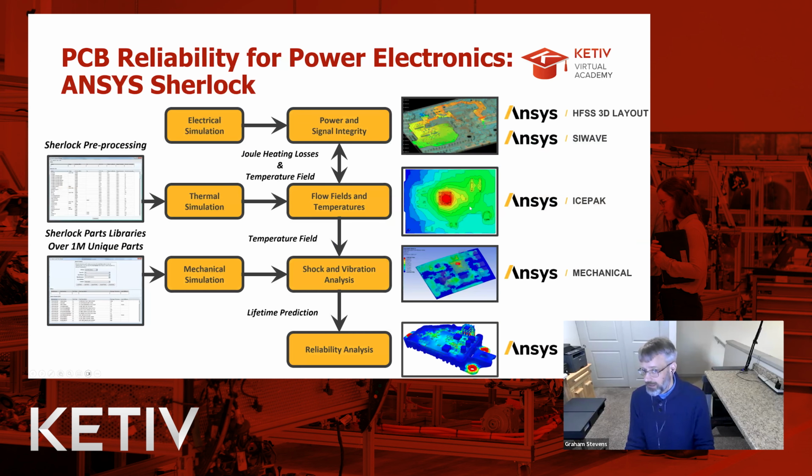And then finally, there's Ansys Sherlock for reliability, where we take all the information from those other previous tests or simulations and put them into a package that can calculate the mean time between failure for each different component. So Sherlock starts with a component database that allows you to get a pretty good initial picture of what your reliability is.